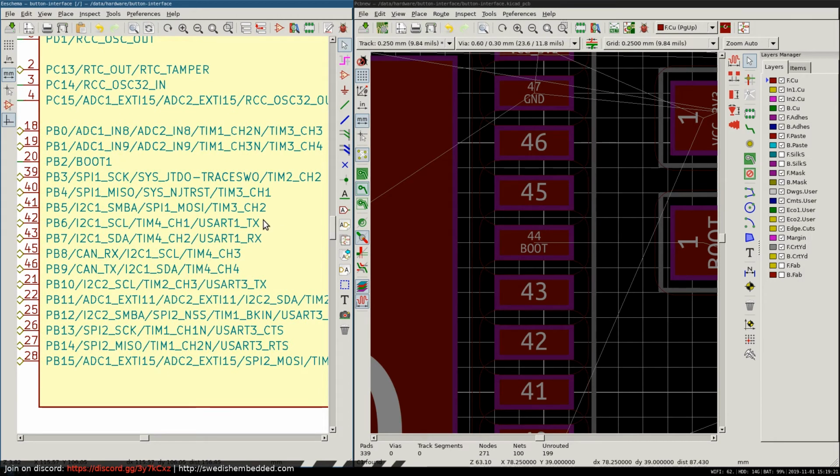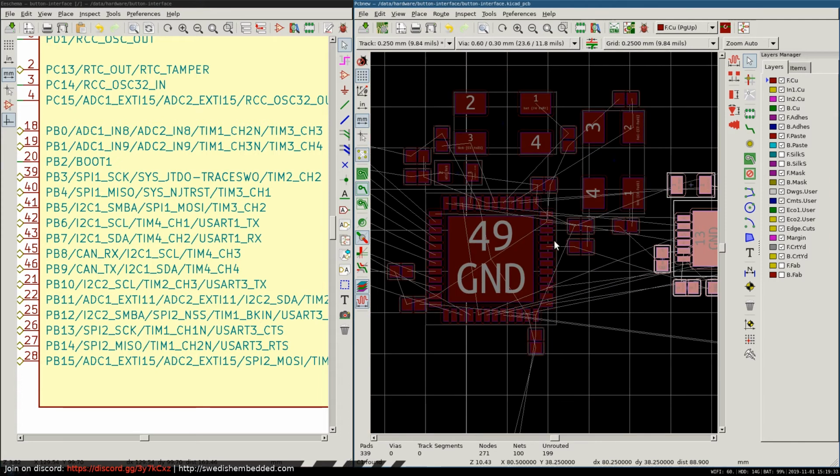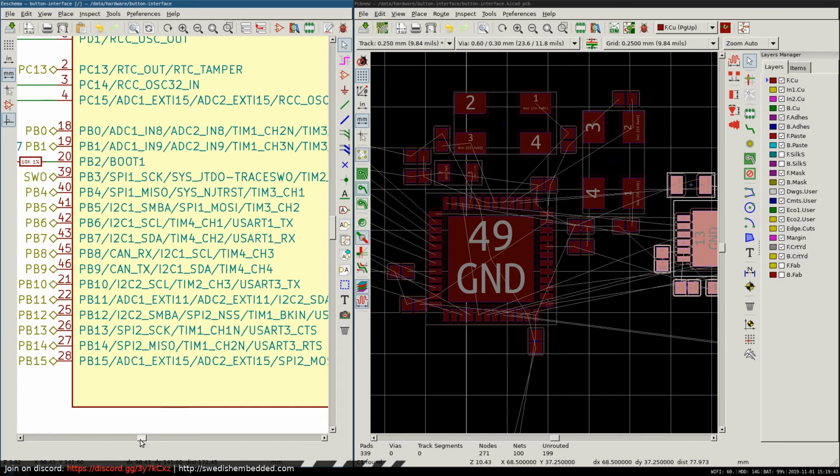So essentially we have UART1, TX, and RX. Usually I use UART1 as the console, the main console for the board. I could use it. I could actually use this RS422 as the main console as well. I could have this debug console on a different UART. That's easy enough to reassign in the device tree.